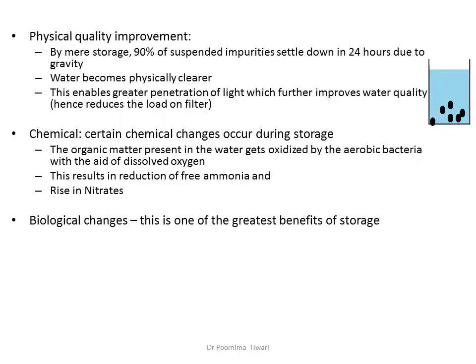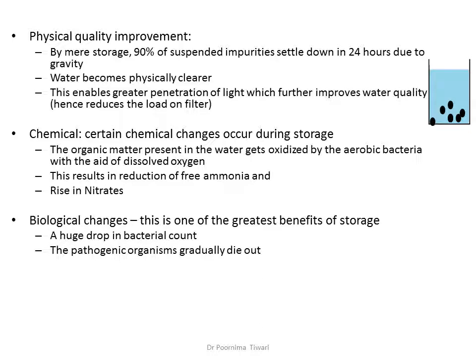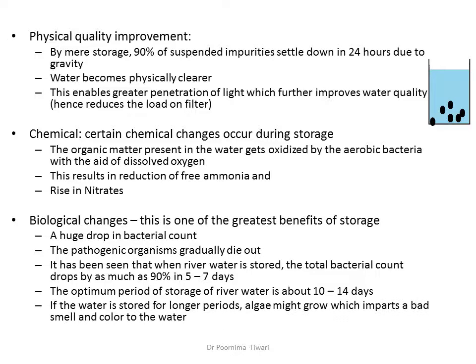Biological changes are one of the greatest benefits of storage. A huge drop in the bacterial count occurs. The pathogenic organisms gradually die out, and it has been seen that when river water is stored, a total bacterial count drops by as much as 90% in 5 to 7 days. The optimum period of storage of river water is 10 to 14 days, and if the water is stored for longer periods, algae might grow, and this imparts a bad smell and color to the water.